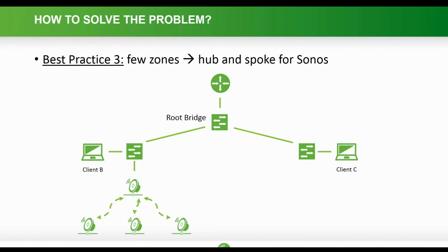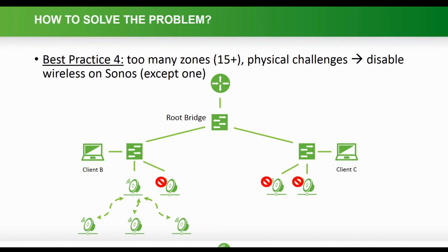This topology only serves you, I think, between 5 and 8 zones, maybe 9. But we've seen dealers who have 15 to 20 Sonos zones in jobs. So that comes to a really complicated topology. What we recommend when you have a really complicated topology is to hardwire Sonos devices to switches as much as possible. Keep one Sonos device hardwired and the others Wi-Fi for those devices that do not have an RJ45 on the back and are completely Wi-Fi. And disable Wi-Fi on those Sonos Connects.